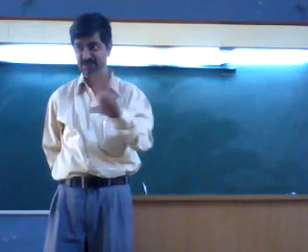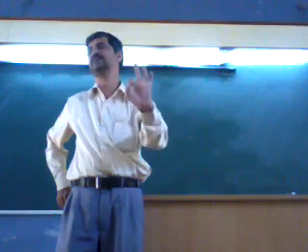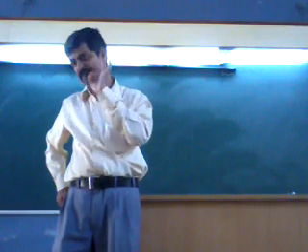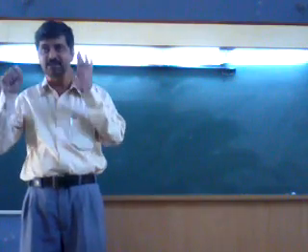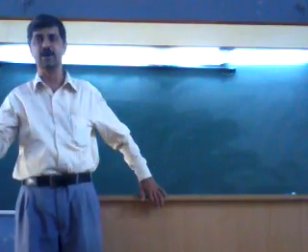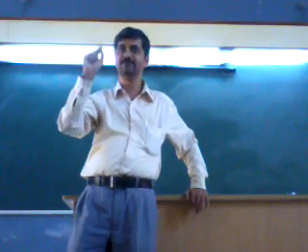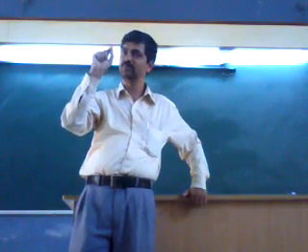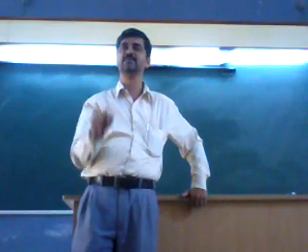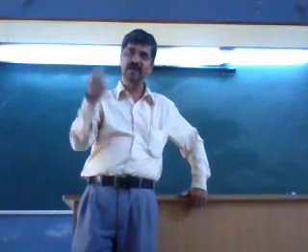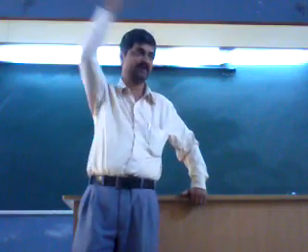Otherwise, there is nothing like imaginary and real. So j squared equals minus 1, and e raised to j theta is cos theta plus j sin theta. When we understand these two things very clearly, we do not get any problem. So what is e raised to st? It is a point which is moving in a 2D plane with respect to time in a particular manner. If s is sigma plus j omega, and sigma is 0, then e raised to st becomes e raised to j omega t, with omega positive or negative. In that case, that becomes movement on the unit circle.